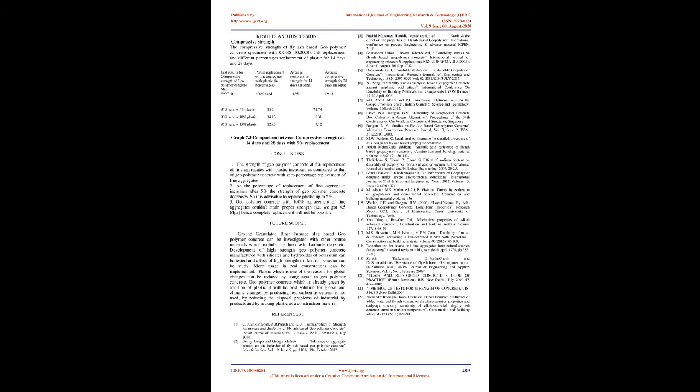Alexandre Rodrigue and José Duchesne reported that for a suitable air void system, good mechanical properties, and low permeability in alkali activated binder systems, appropriate slag fly ash proportioning, water, and admixture quantities are needed. Air entraining admixture quantities of up to 10 times the optimal dosage were necessary to obtain minimal air void properties similar to what is needed for normal Portland cement concrete subjected to freezing conditions. Increasing added water resulted in increasing absorption and decreasing crack counts in concrete. Increasing fly ash content resulted in increasing absorption and decreasing early age crack counts. Increasing both added water and fly ash content resulted in less autogenous shrinkage.